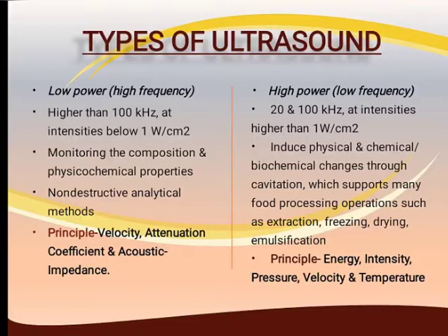And in high power, the frequency is from 20 to 100 kilohertz at intensities higher than 1 watt per centimeter square. It induces physical, chemical and biochemical changes through cavitation. We will further discuss cavitation in the next slides, which supports many food processing operations such as extraction, freezing, drying, emulsification. Its principle depends on energy, intensity, pressure, velocity, and temperature.